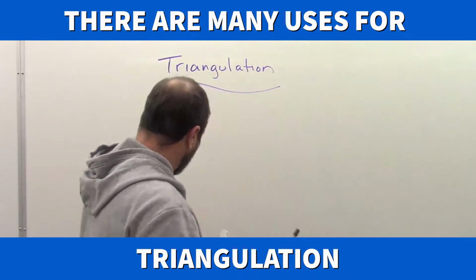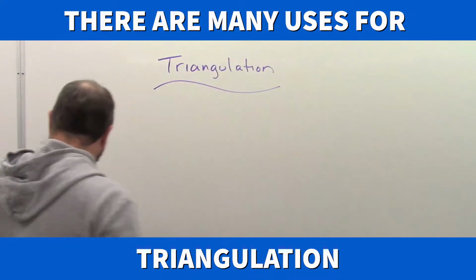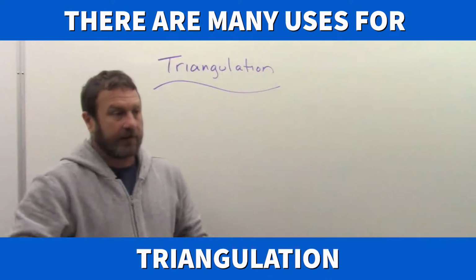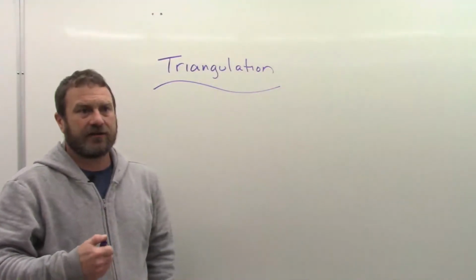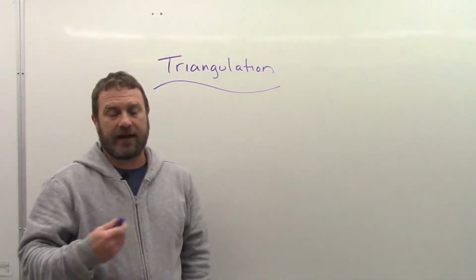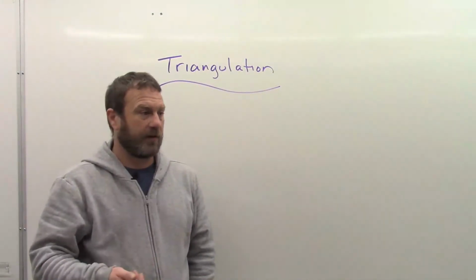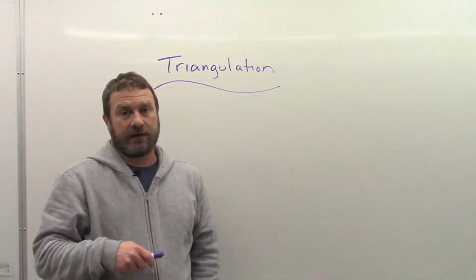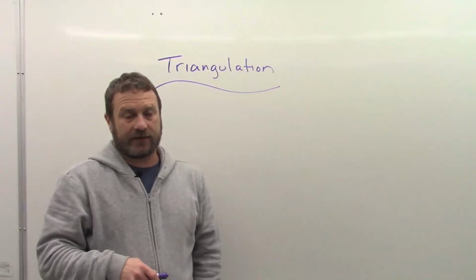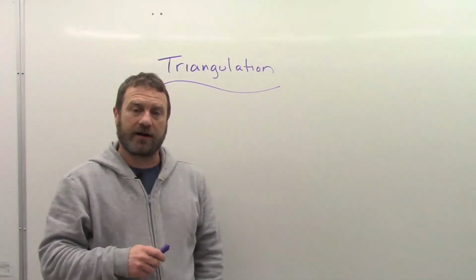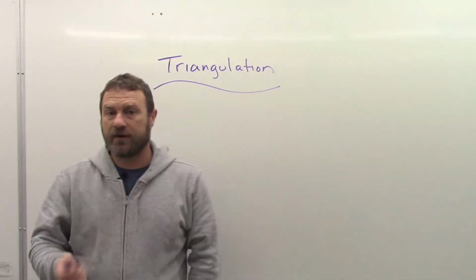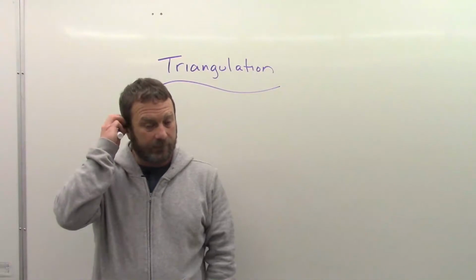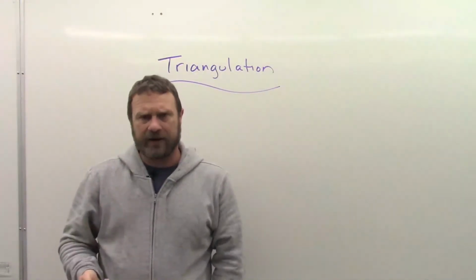But in this chapter, we're more referring to triangulation in pattern development. So we're looking at our layout. Okay, so the basics of triangulation: two known points to create a third, and that's a fairly simple process. Where we run into some difficulties is coming up with the lengths. When we start our triangulation process, we don't always have what we refer to as true lengths in our plan view or in elevation view.